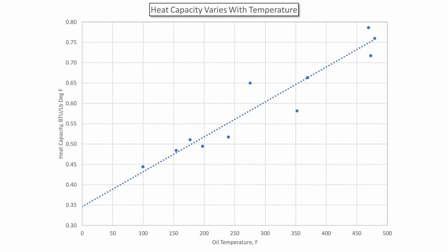In addition to the components of a mixture, the temperature and pressure of a mixture determine some of the properties, and this graph is just meant to show that heat capacity varies by a significant amount, almost 50%, over the normal range of crude oil heat capacity that we would be calculating for the heat exchangers that we consider. So we need to make really sure that we're using the right heat capacity that's relevant for the temperature that we're talking about, even if we're not dealing with vaporization.